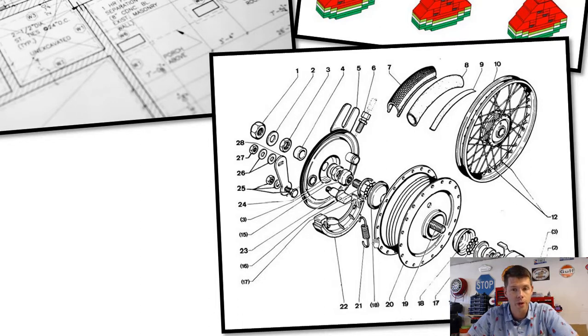So I can go to Toyota's website and say, okay, I need 2 exhaust studs because the ones that hold the exhaust manifold on were so corroded and the threads were all messed up, so I'm going to take those out and put 2 new ones into the cylinder head before I put the exhaust back onto the cylinder head. And I need a gasket to go in between there, and there's all the little nuts and bolts that hold the exhaust manifold to the cylinder head. And all these things have their own different part numbers and their own unique prices and whether or not they're even available anymore.